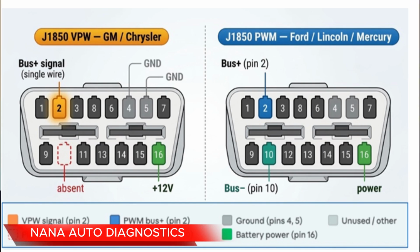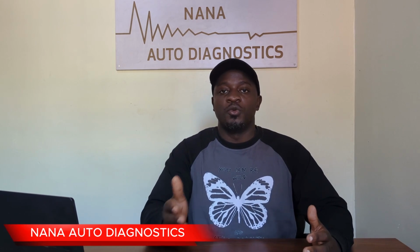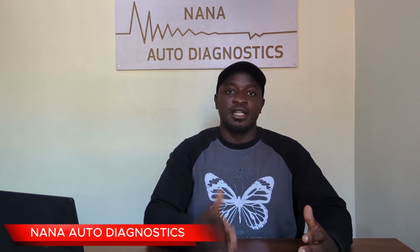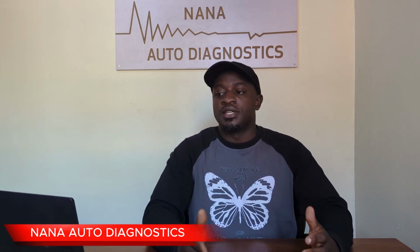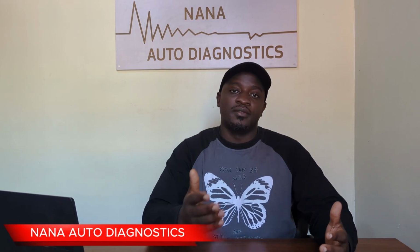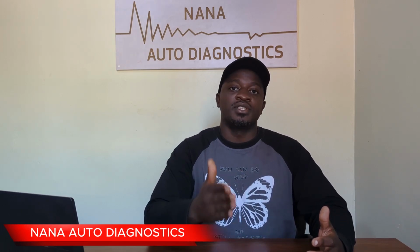Why are we going through all this? When you are dealing with the VPW or the PWM, you will use different testing methods and you will have to expect different results. For instance, when you are dealing with the VPW, you expect your voltages to range between 0 and 7, and you only have a single wire.